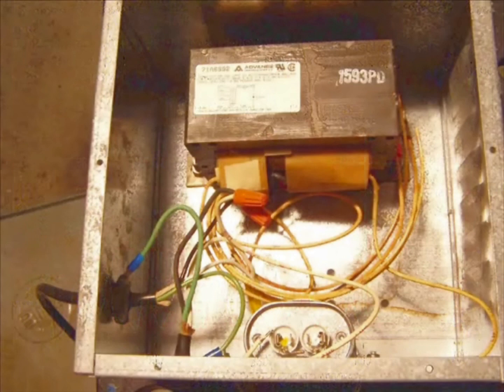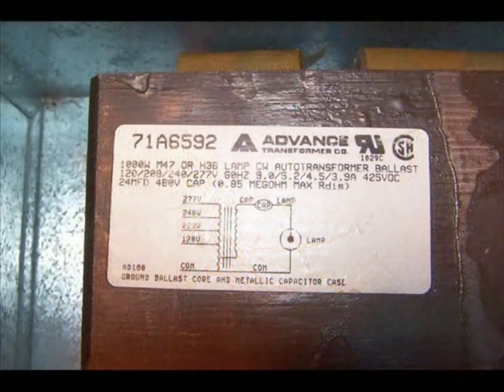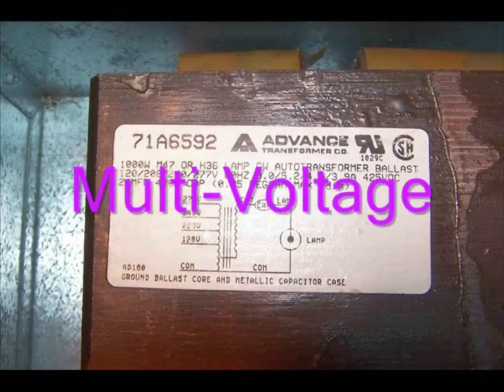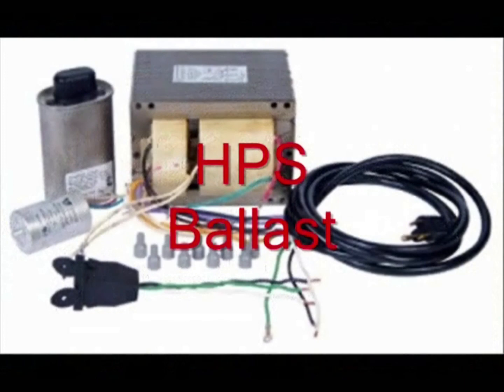All high-intensity discharge lights must be ignited by some sort of electrical ballast. The high-intensity discharge transformer ballast has been around for decades and is still widely used because of proven reliability. Its main component, the auto transformer, is often a multi-voltage type which can use one of several different available input voltages.